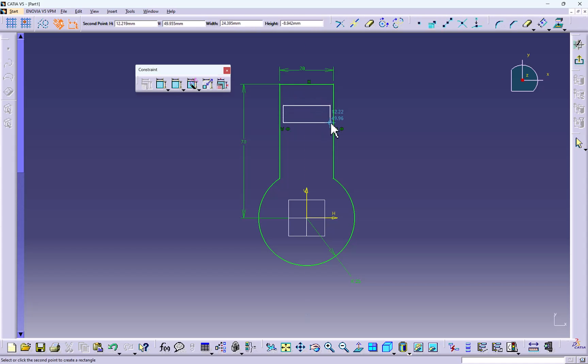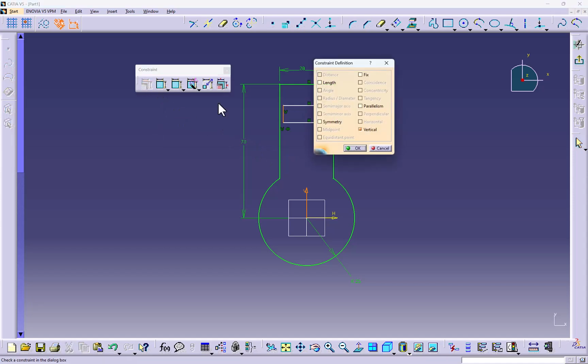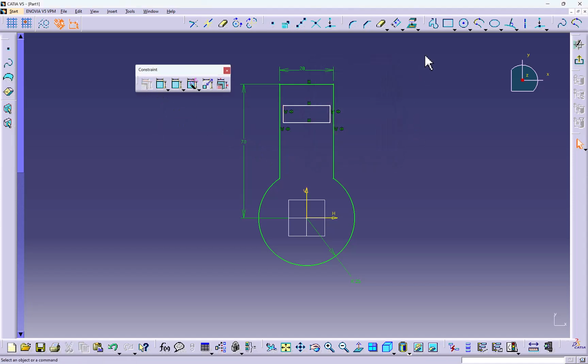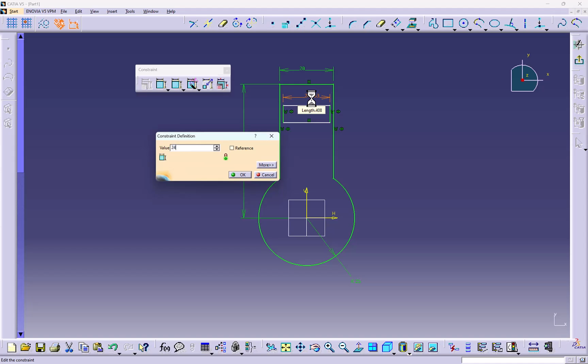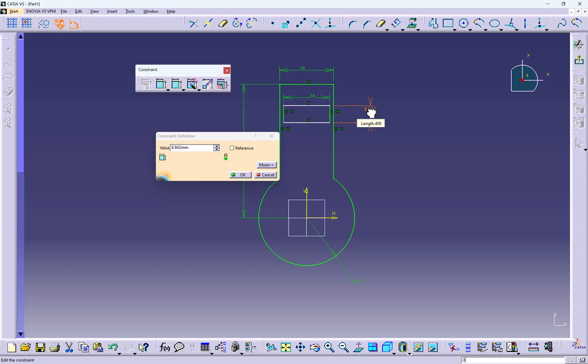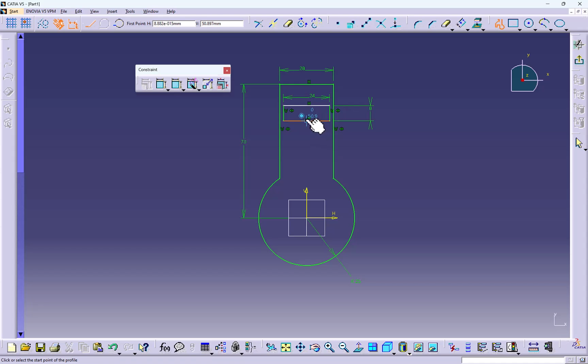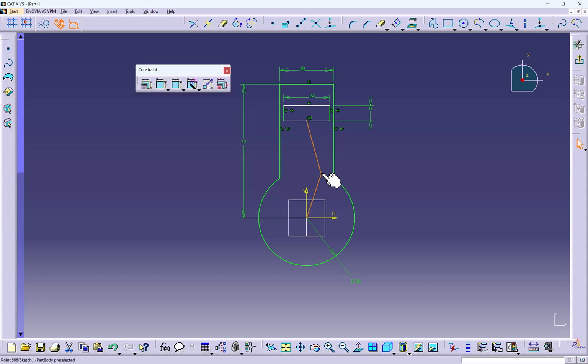Now I'll make one piston arrangement here. I'll create one piston and arrange it exactly at the center first with the help of the symmetry method. Now I'll define exactly the sizes of this particular piston: 24, and we can specify 8. So we'll put it here 8, and also we'll add a connecting rod between them. We'll take the connecting rod, pick this point, and define how the connecting rod will go to the origin.